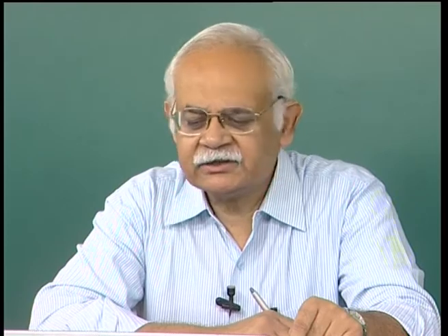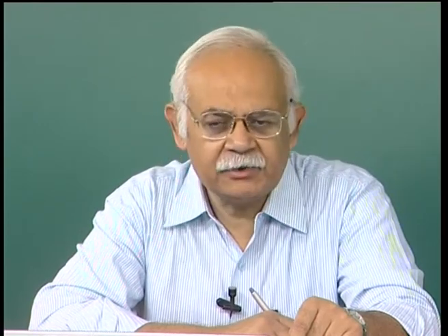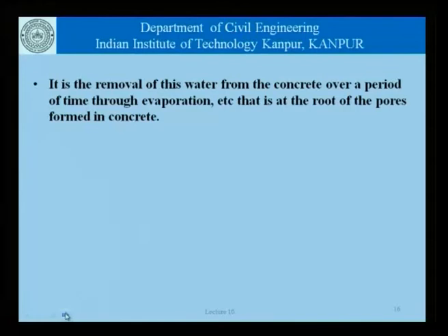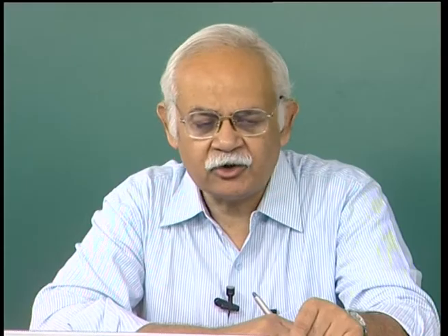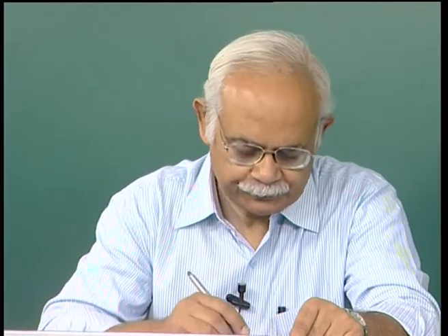Now, as far as this excess water is concerned, which is available in the matrix, what happens to that? It is the removal of this water from the concrete over a period of time through evaporation and so on, that is at the root of the pores that are formed in concrete. So, this water which is left behind gradually evaporates, and this evaporation leaves us with a concrete which has pore spaces which were otherwise occupied by the excess water.